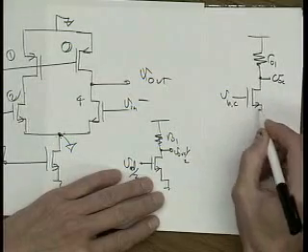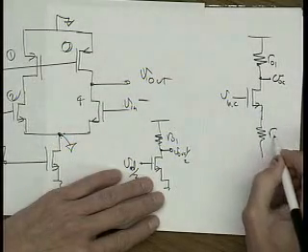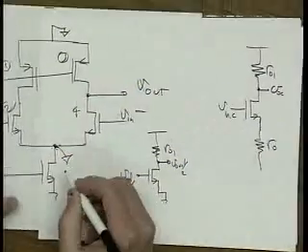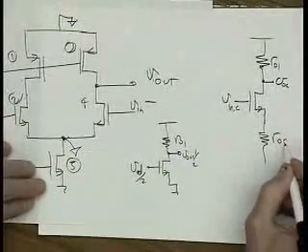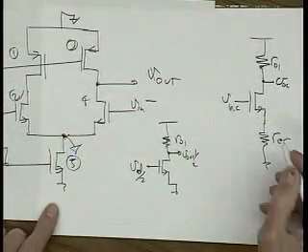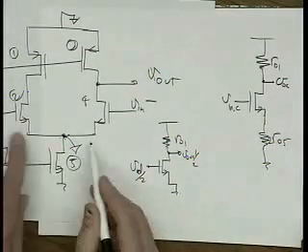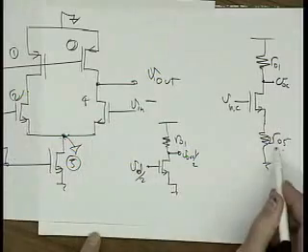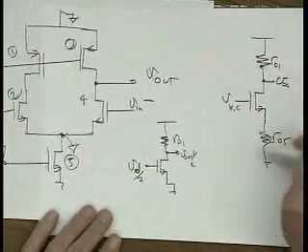We're doing the half circuit analysis here, and then we go down into R05. To do our half circuit analysis, remember we make this twice as big: we split it into two parts, so we have a 2R05 down here in the source. So this is our common mode half circuit.